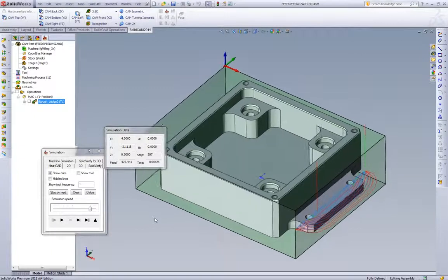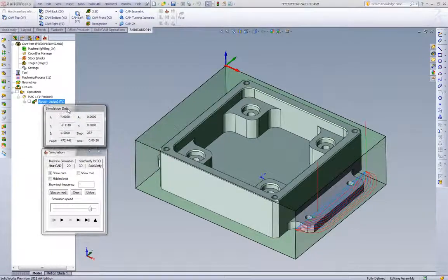As I talked about earlier in the video, we used a 4-flute end mill. Generally, most customers cutting aluminum are using 2-flute and 3-flute end mills. Generally, this is done because in aluminum you can overload your chip load to very high amounts. So in standard steel, with a 1/2" end mill, we'd generally be running around, let's say, a 3 to 3.5 thou chip load. When it comes to aluminum, we can overload the chip thickness all the way up to like 6, 7, 8 thousandths. But when we do that, we need to have chip evacuation. So this is generally why in aluminum we're using 2 and 3-flute end mills.